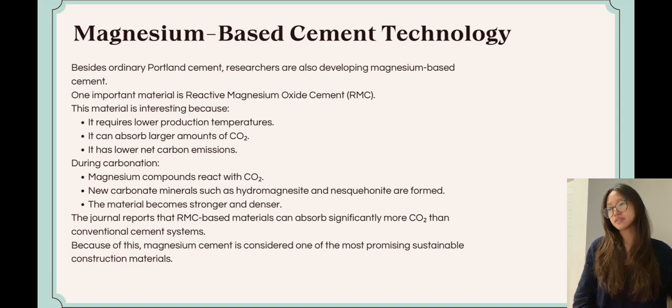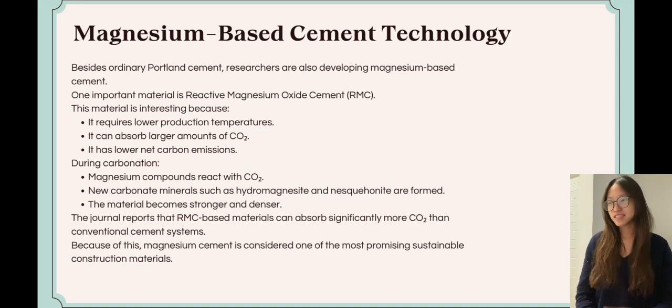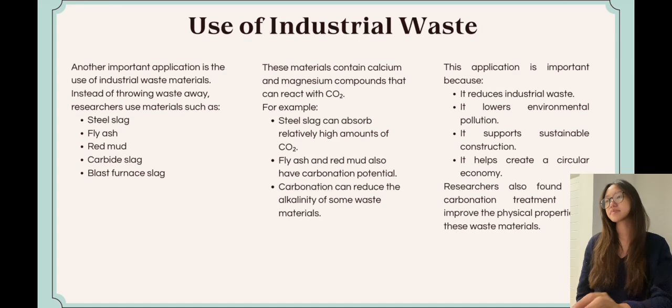During carbonation, magnesium compounds react with carbon dioxide. New carbonate minerals such as hydromagnesite and nesquehonite are formed. The material becomes stronger and denser. The journal reports that RMC-based materials can absorb significantly more carbon dioxide than conventional cement systems. Because of this, magnesium cement is considered one of the most promising sustainable construction materials.